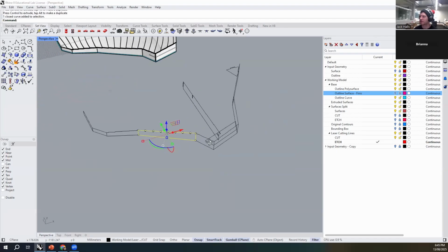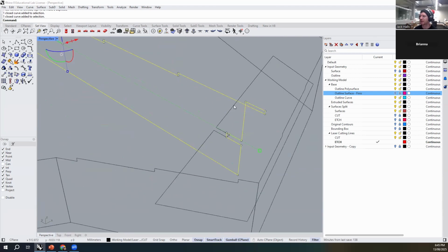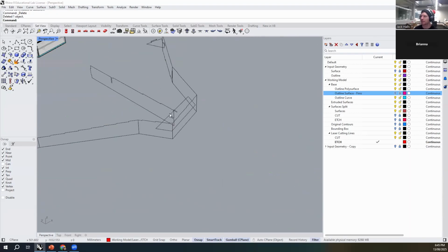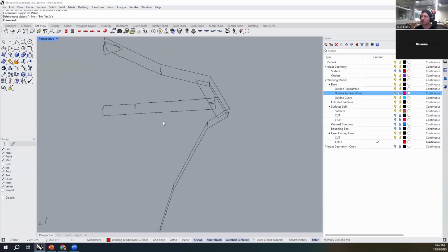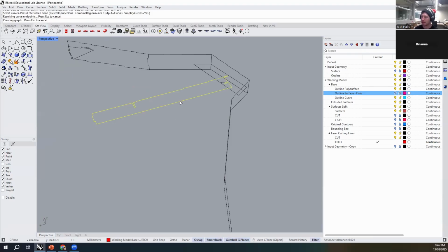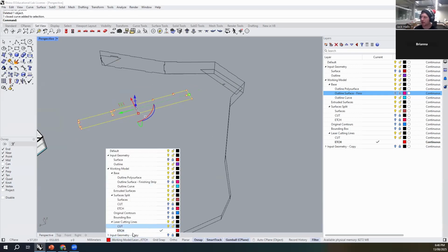And then we need to do that for all of this geometry. And obviously it's all sitting on different planes and whatnot. This is an opportunity that I can take to fix things as well. So sometimes if things didn't work in the modeling, we don't necessarily need to remodel that or anything. What I can do is I can just project that to the C-plane, yes. And if I don't want this little bit on the end, I can just use my curve Boolean command again, right? So curve Boolean, like that, that's inside, and that cut off that little extra piece for me. It's put it on the wrong layer because I put active.